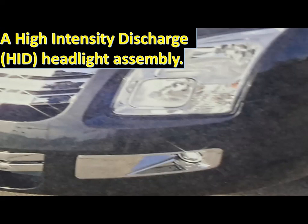Approximately 15,000 to 25,000 volts are required to initially force current across the air gap between the electrodes. Once this air gap is bridged with a stream of electrons, about 80 volts are required to maintain the current flow across the gap.